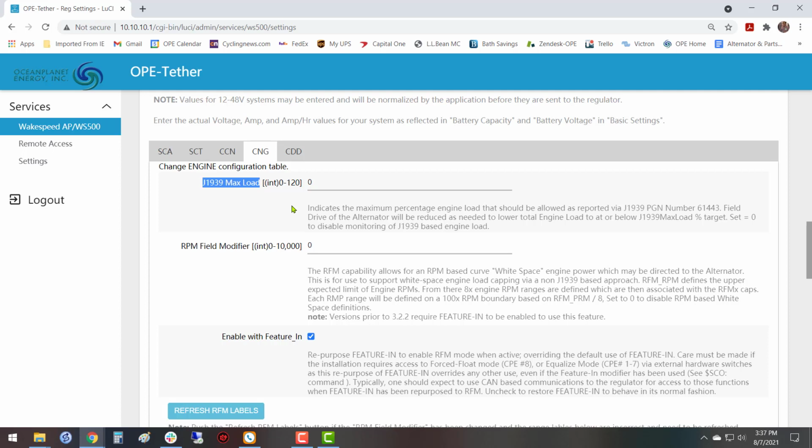With the newer fancy engines, they have limitations on how much fuel can be applied in order to reduce emissions so you don't soot. And for a given target RPM, there's a CAN bus figure that comes out over the CAN bus communications that says how much fuel it's applying. So you could say, one we've used before is 60%.